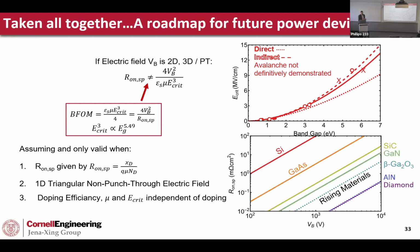As well, if we just treat this as an always true analytical formula, let's say you have an unoptimized device and you should be getting 1,000 volts, but you get 200 volts. Well, this formula would then predict that your on resistance should be 25 times lower than it should be. And that's clearly not accurate. It's the same epi, you just haven't optimized it. So with that, I hope we're all on the same page, and I've explained where this BFOM comes from and where its shortcomings are.